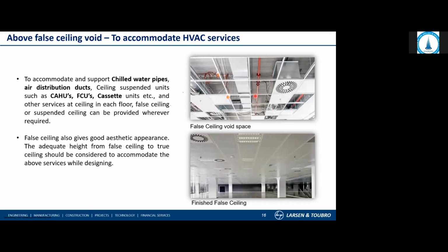That takes a lot more space. It depends upon the arrangement of the supporting structure of the false ceiling, but in some arrangements it takes a lot more space. So while doing the design, we have to take into consideration the total false ceiling depth, so that no service touches the false ceiling, to avoid any vibration in it.